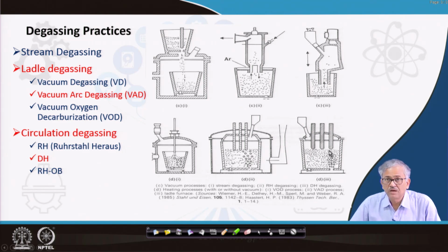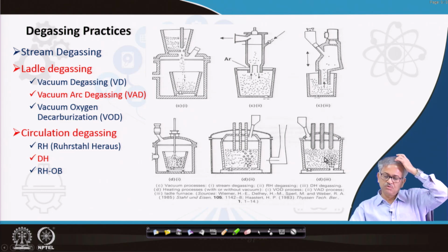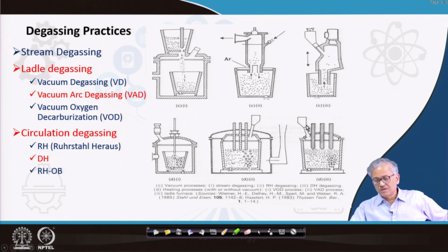And this is called the ladle furnace. This is basically a one atmosphere process, and here no vacuum is there. Here you have alloying additions, and an arcing system for temperature compensation and gas stirring. We will talk about that thing. Here it is the LF process.